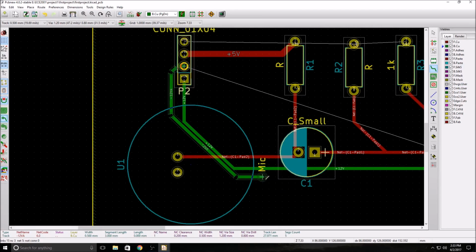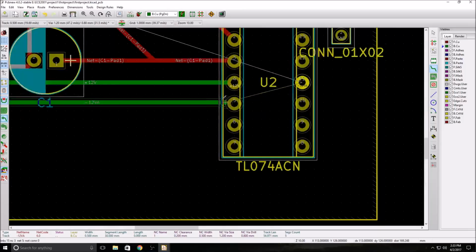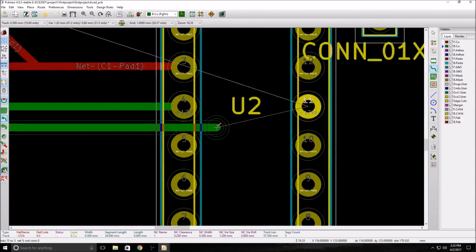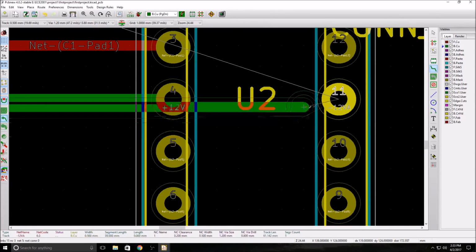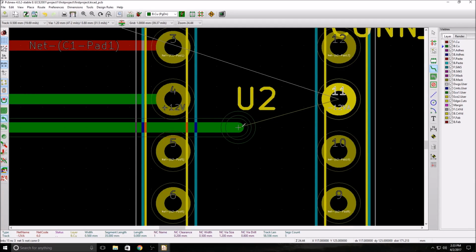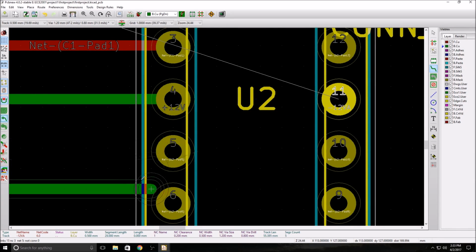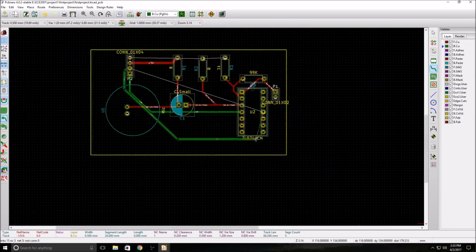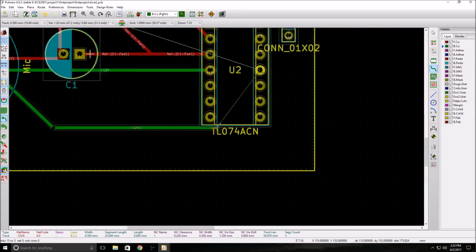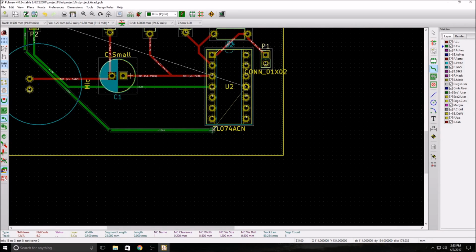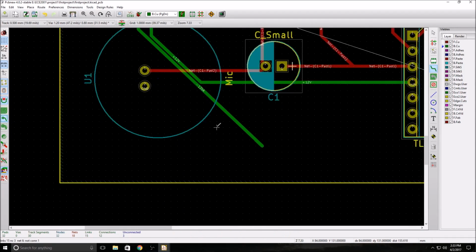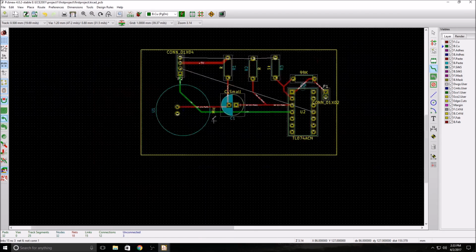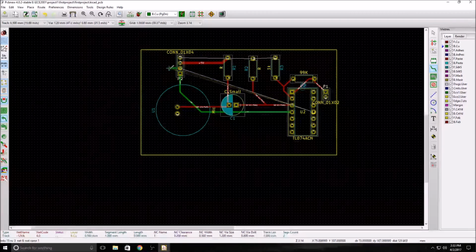We can get right close up with the tolerance. Now it says that I can fit it through here, but let's see if we can actually connect it. See, it won't let me connect it because it's within its tolerance. So we'll have to move this down, and then up. Actually, cancel. We'll move this over just a little bit so that it's not as bad.